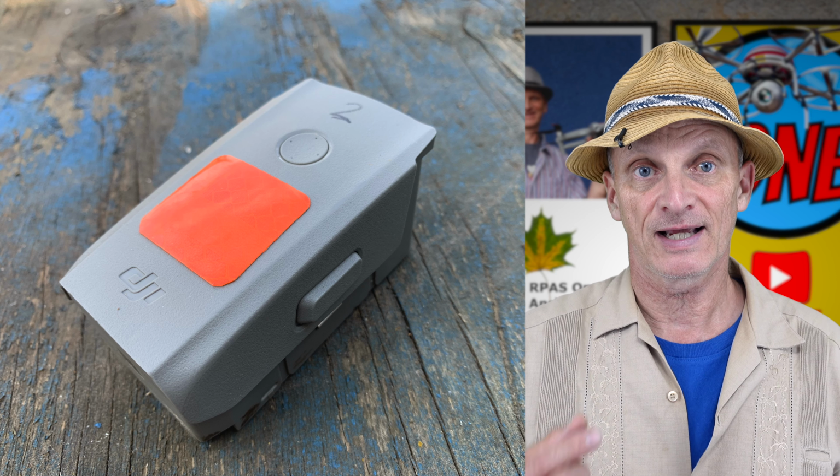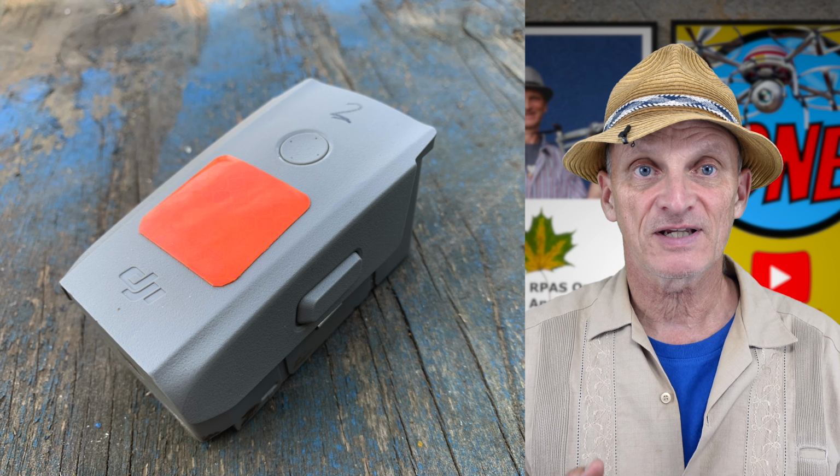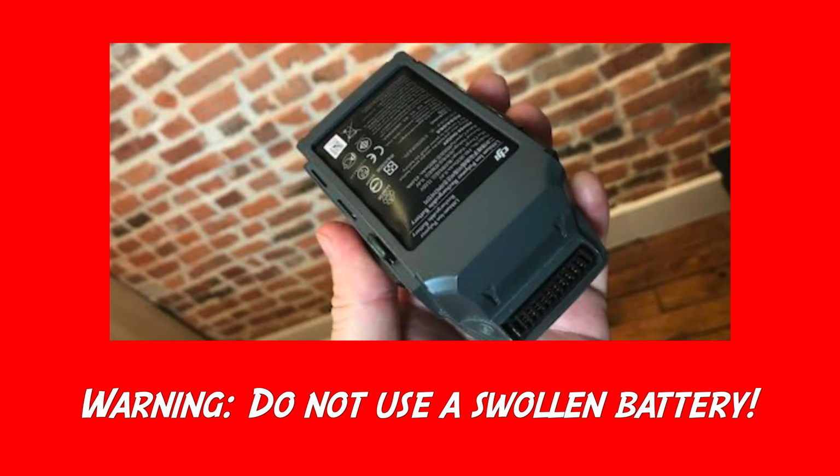LiPo batteries are light and powerful, but they can be volatile. Things like overcharging, deep discharging or physical damage can make them pretty unsafe. It's best to store them at about 50% of charge. Don't use a swollen battery.